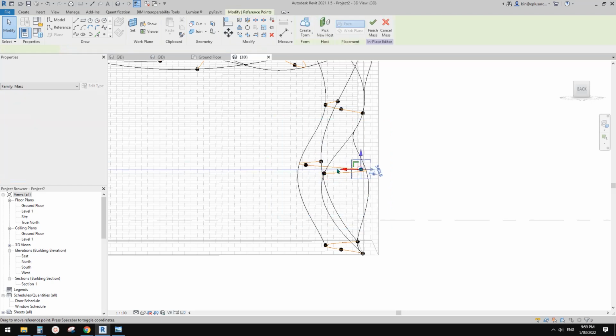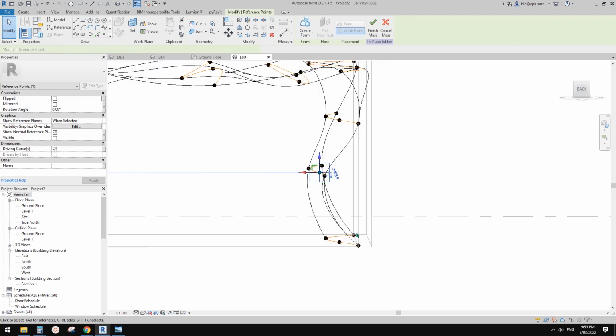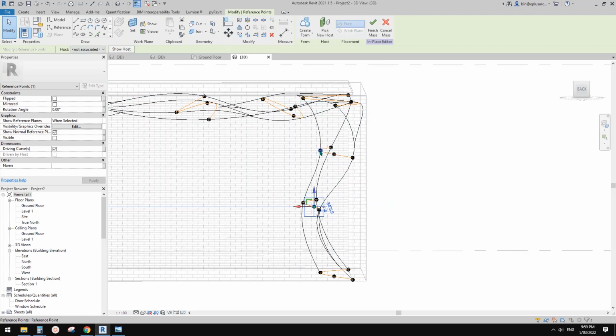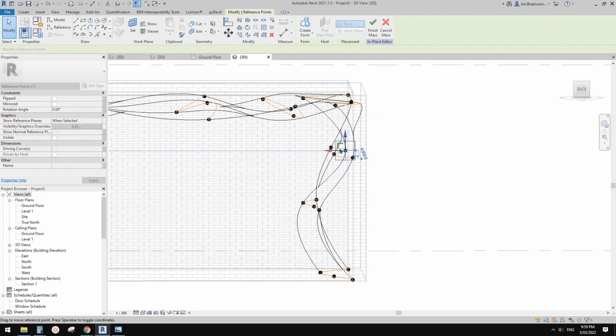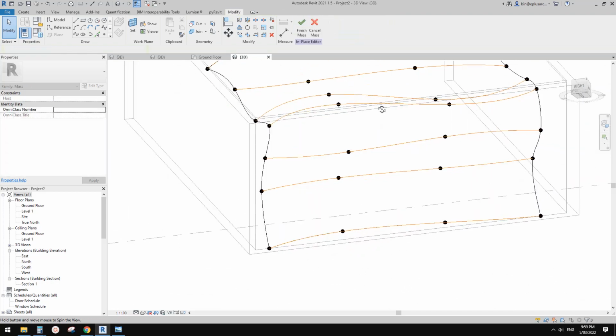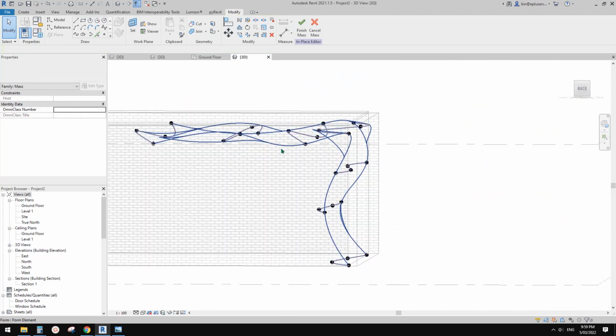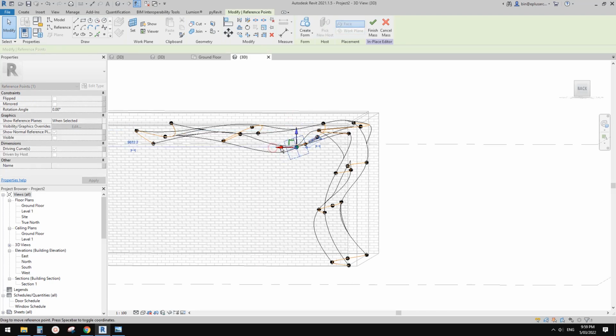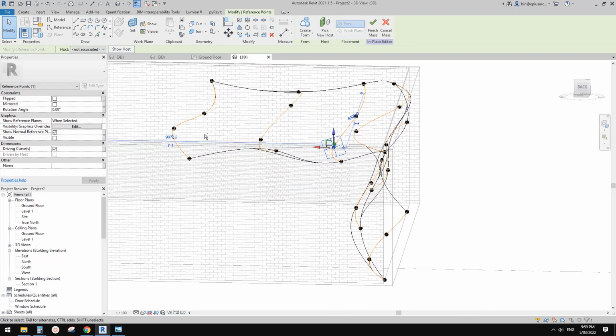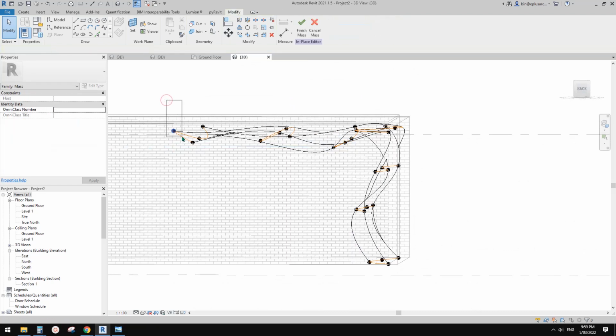Most of these points at the second reference lines go out and go in. So it's all up to you. You can even just place that adaptive family, see, have a look. If you don't like it, you can come back to adjust these points.